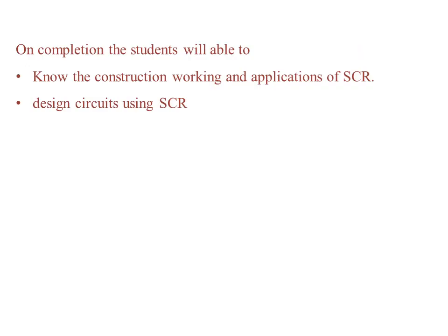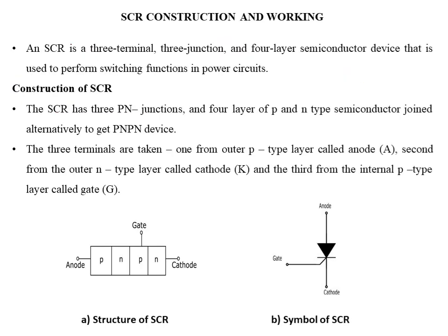On completion, the students will be able to know the construction, working and applications of SCR, and circuit design using SCR. SCR construction and working. An SCR is a 3-terminal, 3-junction and 4-layer semiconductor device that is used to perform switching functions in power circuits. Construction of SCR.